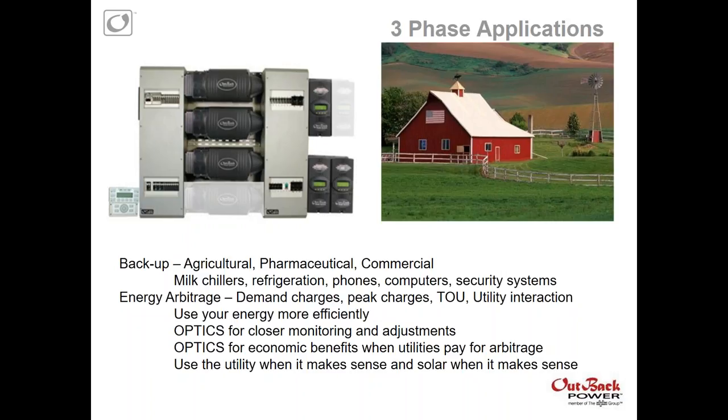Well, they're never allowed to go below 59.7 hertz on our grid, or they're outside the ANSI limits and they get fined, at least in the US. I believe it's all in North America. But essentially, they've got voltage and frequency limits. Every time they have to push that power further out one of those circuits, they have more and more difficulty keeping it within those limits. Well, the answer is energy storage and a grid interactive smart inverter like the Radian.